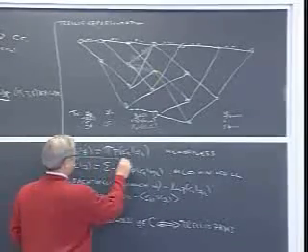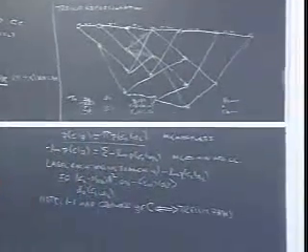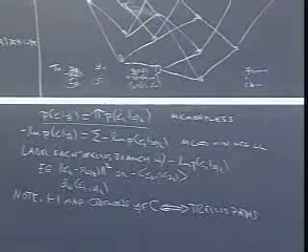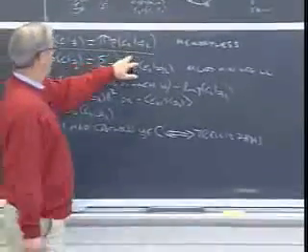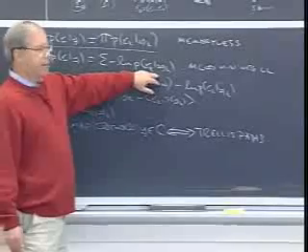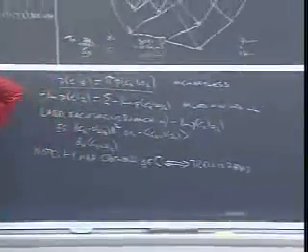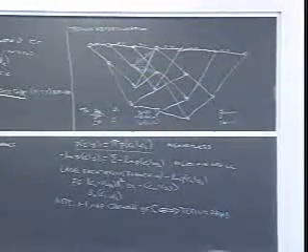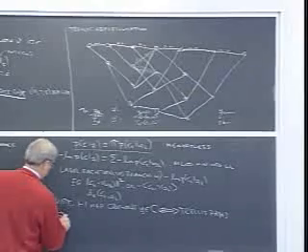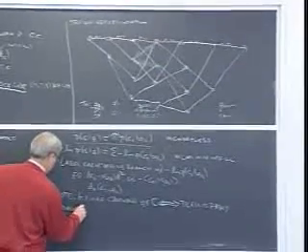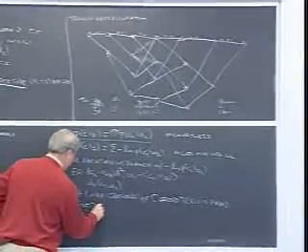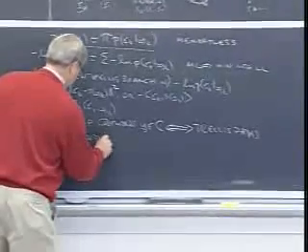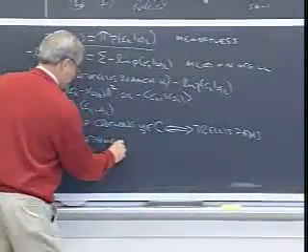The independent transmission allows me to break it up into a symbol by symbol or time by time expression. So I can simply accumulate over this sum right here. All right, and I'm just looking for the minimum sum over all the possible ways I could get through this trellis. So now we translated this into finding the minimum cost path through a graph with a very special structure, nice regular structure.